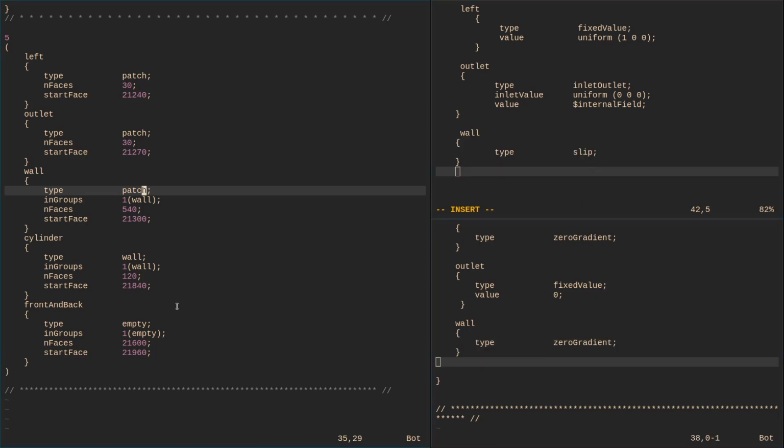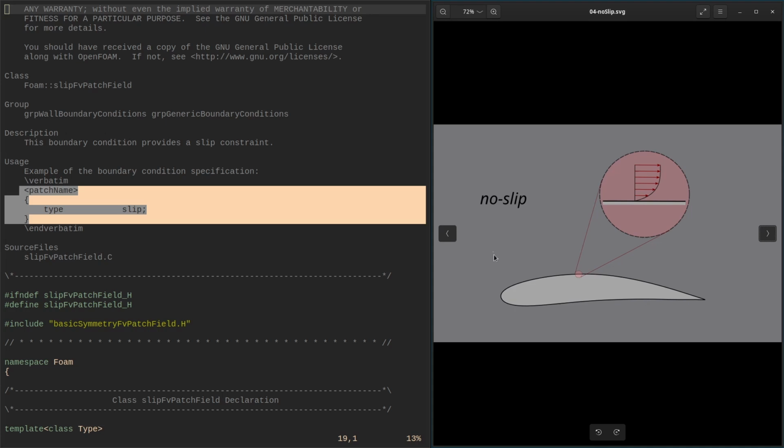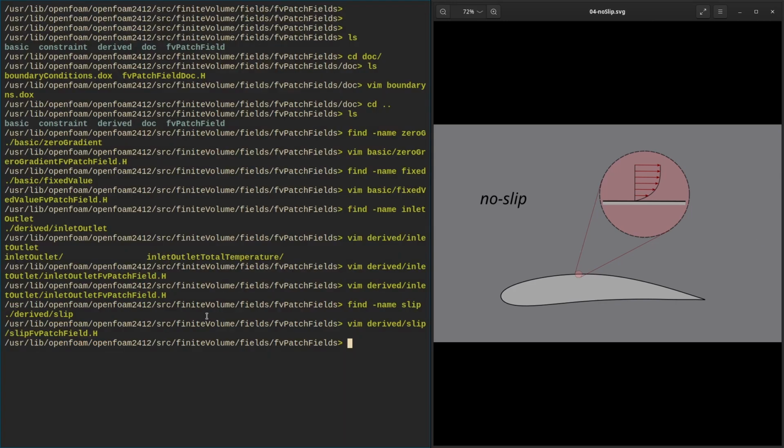Okay, the second type for wall velocity is no slip condition. In this case, we have a fluid that sticks to the wall. If the wall is stationary, the velocity at the wall is zero. This comes from viscosity. Friction between the fluid and the surface slows the flow down to a complete stop at the wall. We use no slip condition when we are solving for viscous flow, boundary layer development, turbulence, and drag. In situations like pipe flow, flow over a car or aircraft, or heat exchangers.